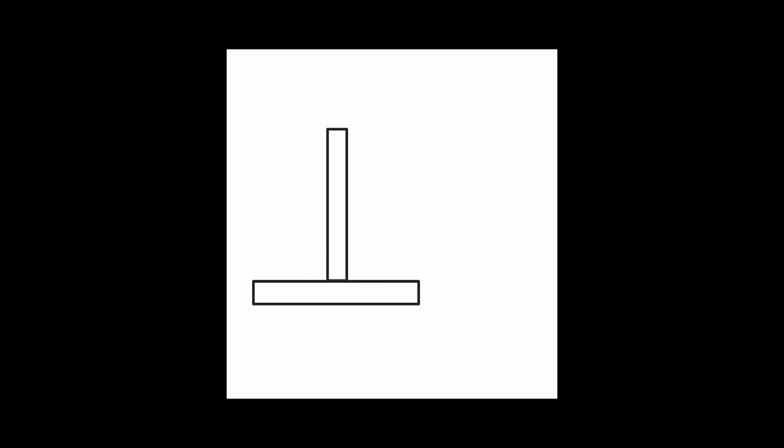So how would you apply this when given an actual project to work on? Well, let's take a T-joint just to keep it simple. So on a blueprint, if you're given a T-joint and on the reference line you see that there's a fillet weld symbol on the arrow side of the reference line, where do you think the weld would go? In the event that you're given a weld symbol on the arrow side of the reference line, you simply look and see where the reference line is pointing to. So the joint that the arrow is pointing to is going to be where you place the weld.